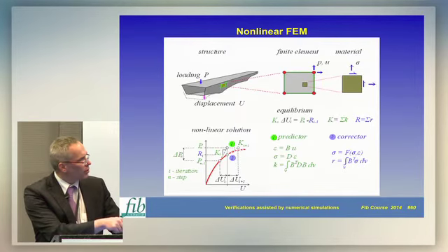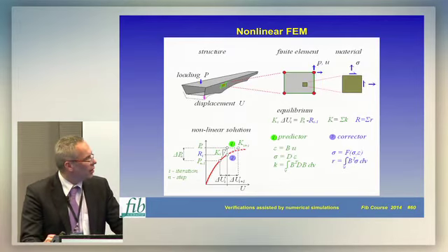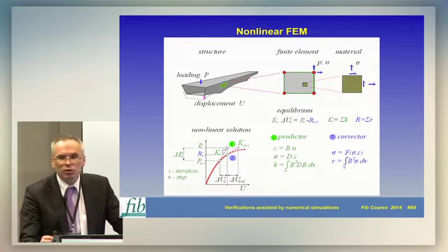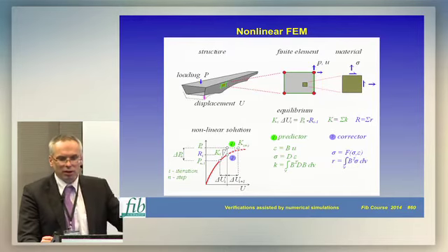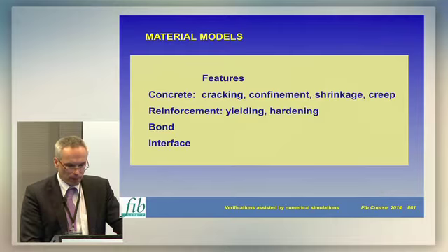by calculating the proper stresses in the material, and then by integrating them we come up with some internal forces, and then the difference between the internal forces and applied forces introduces some residuals, which are then iteratively redistributed throughout the model.